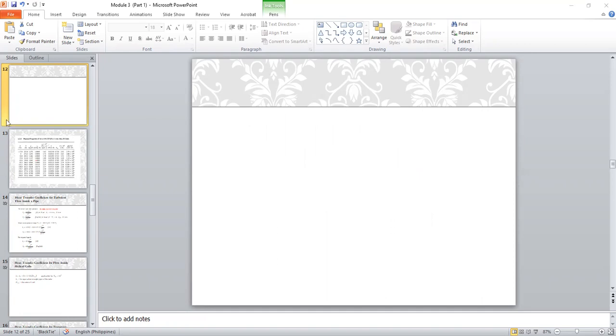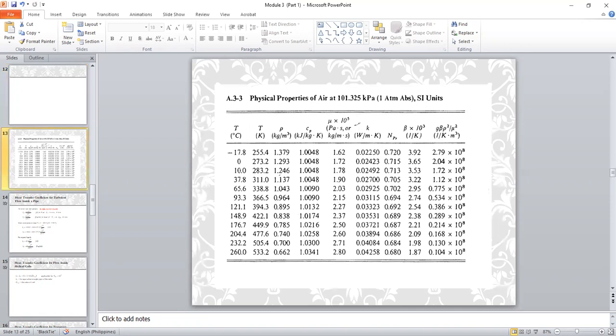And this is the table that I'm referring to. So in the table, for this particular temperature class, again, we already got the U sub B, the bulk viscosity, and we need to read simply the Prandtl number here. That's the Prandtl number. And there's another viscosity that you're going to take from this table based on the wall temperature.